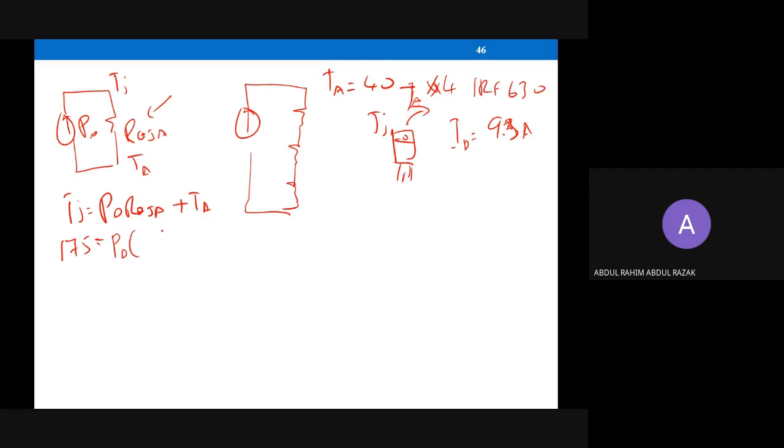What is R thermal JA for this device? You can open page number 2. In the last table, thermal resistance parameters, degrees C per watt, there is R thermal JC, R thermal CS, and R thermal JA. We have two values for R thermal JA. In the parameter column you can see note 4 and note 5. Junction to ambient, note 5, applies if you mount on the PCB.